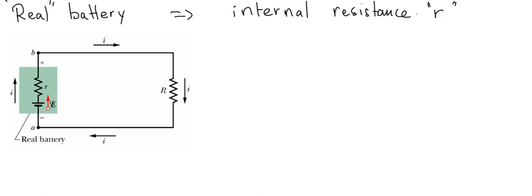So how can we calculate the current in the circuit? We do it the same way. We choose a point and a path, this time counterclockwise, and we write the loop rule. The direction of the path is opposite to the direction of the current, so the difference in potential across this resistor is plus Ri, plus ri.